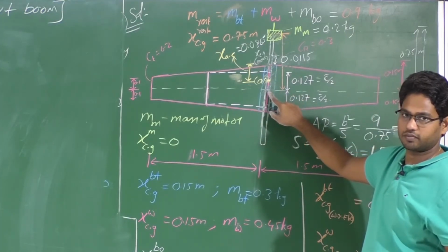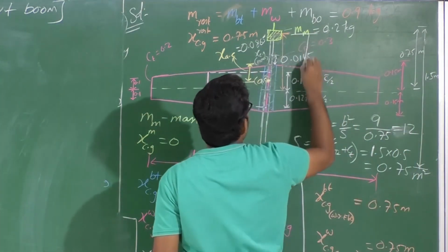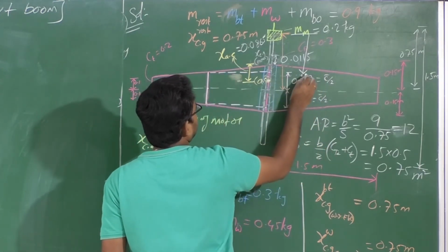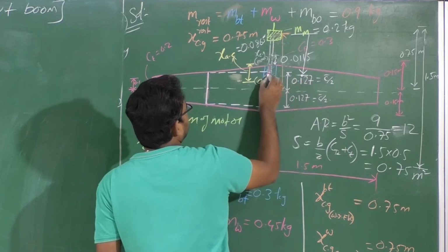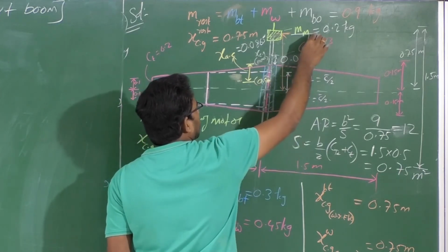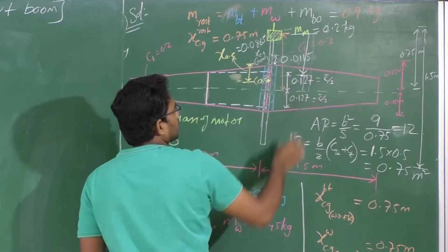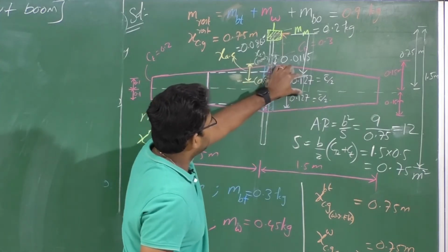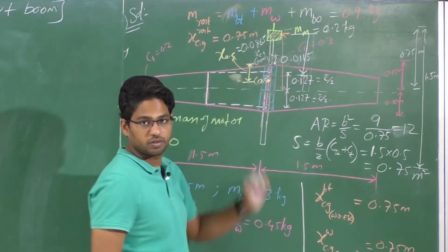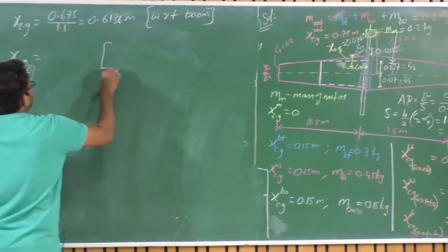Am I correct? CG and midpoint, let us say the CG is somewhere here, this particular point. On this axis I just projected this at this particular point. So what I am trying to do is subtract this distance from this entire distance, right? What I end up with is this particular distance. Now I have CR by 2. If I subtract this, I have that particular location with respect to the leading edge of the root chord. Okay, got it?